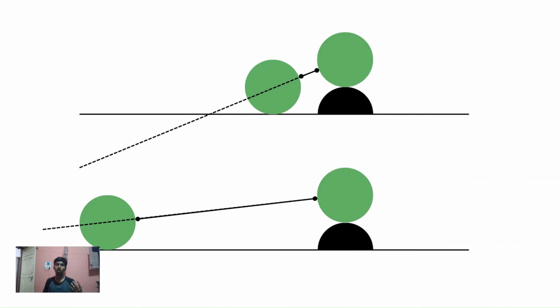Now, is it always good to have longer wheelbases? No, not really. When you have the comfort of longer wheelbase cars, at the same time, you must take into consideration that they are not very responsive, say in the case of taking a turn. Of course, the rider sitting inside the car will not feel it, but at the same time, the car should make the turn, right? Say you're taking a sharp turn.